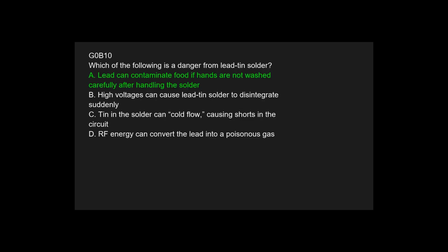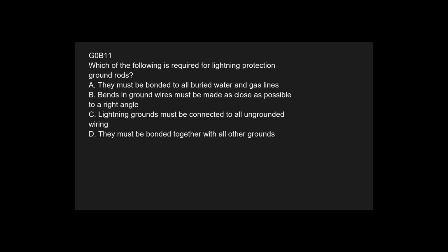The correct answer is A. Lead can contaminate food if hands are not washed carefully after handling the solder. And question, which of the following is required for lightning protection ground rods? The correct answer is D. They must be bonded together with all other grounds.